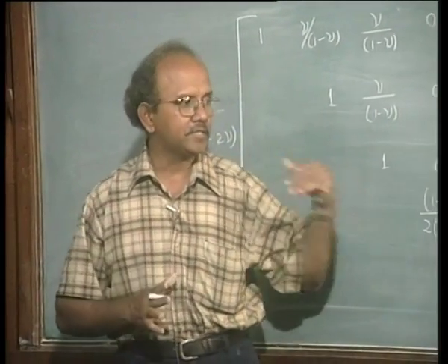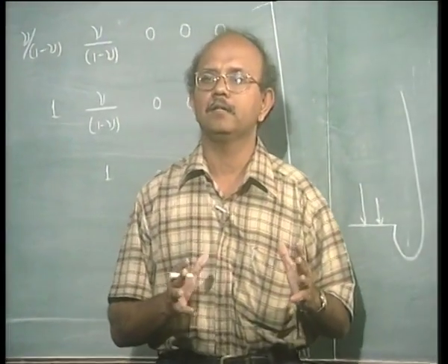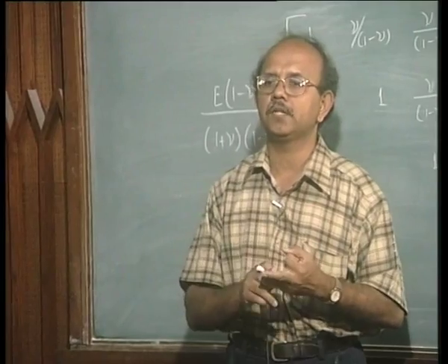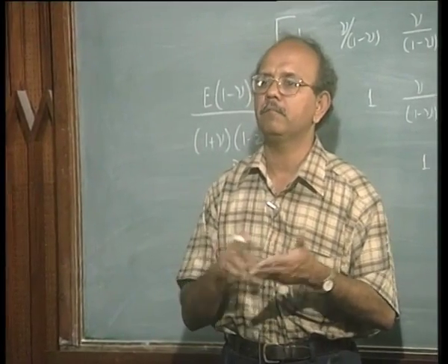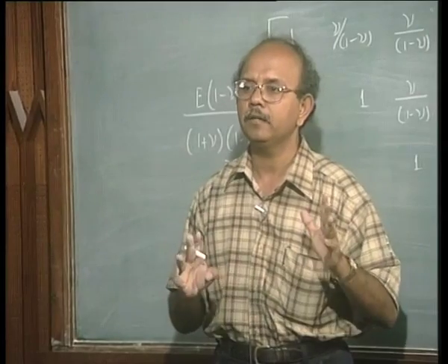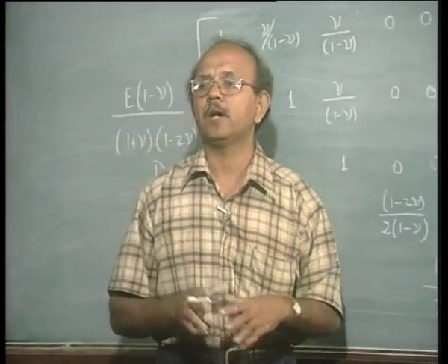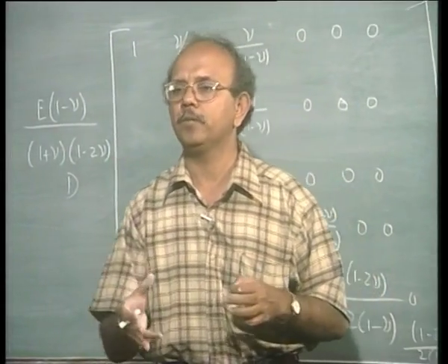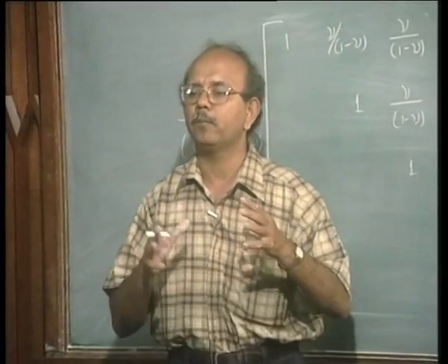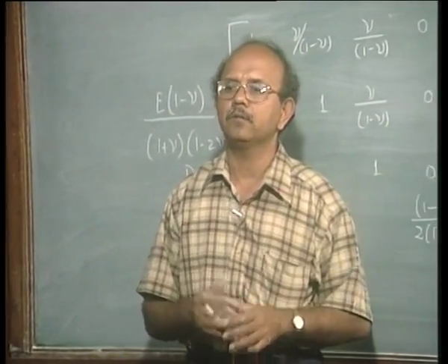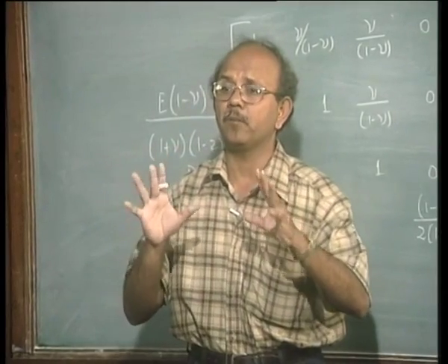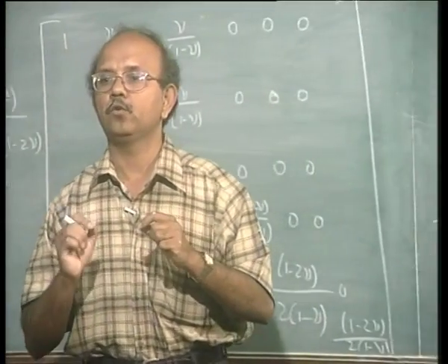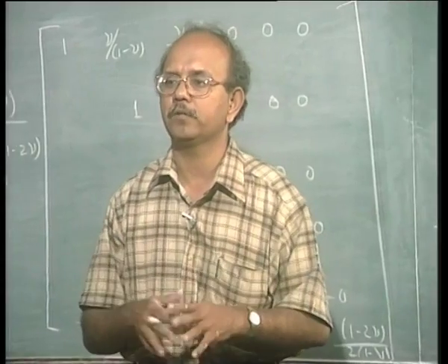So at the end of these discussions, you know that the major elements are solid element, plane strain, plane stress, axisymmetric, beam and shell, right. These are the major types of elements apart from a simple spring element. Of course, I have included bar into beam. If you want, you can exclude it and talk about a bar or a truss element, and so on. These are the major types of elements, and you also know what the degrees of freedom are for each of the nodes that present this element.